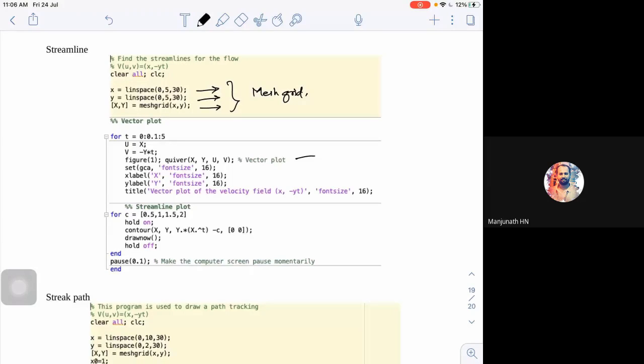Okay. So now I need to define this particular time point. Look at this. If this time point is smaller, so t is equal to 0, instead of 0.1, if I keep it as 0.01, I'll get finer points. Even your mesh points also, I have kept it as a coarse 30, 30. I can go with 100, 100 or 200. So the more the number of mesh points, the finer will be the mesh plot. At the same time, your x and y coordinates, maybe 5 and 5 are defined. I can go with 10 for the x and 2 for the y.